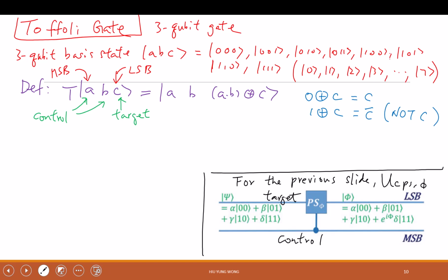Cycle time, right? So you mean how long it takes to complete the gate operation. In classical logic, you need to wait for a signal to propagate. That is the delay time of a gate. For example, for a NOT gate, you have a low-to-high rise at the input, and then you look at the output to see how long it takes to go from high to low, 50 to 50, whatever. That is the delay time.